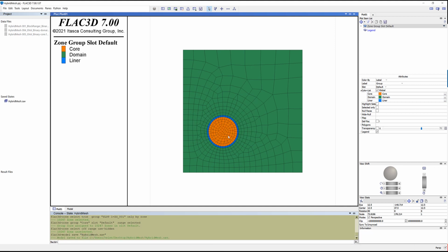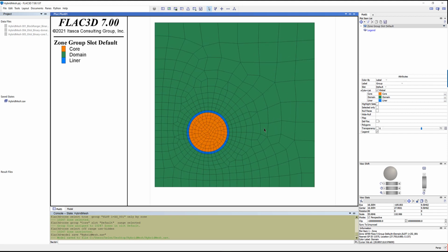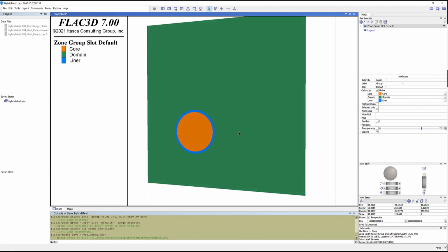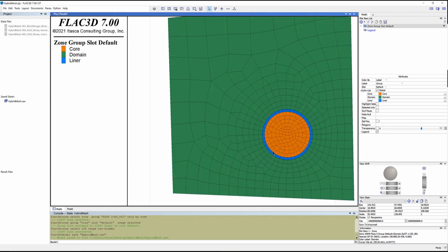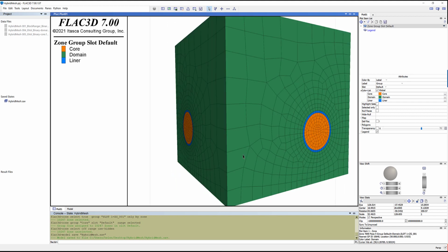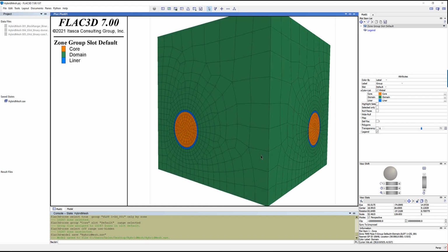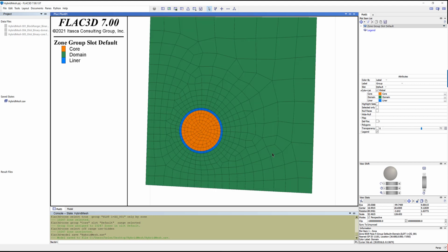Now the model state is visible under saved states in the project pane. By saving the project, the current project state is saved into a project file. By saving the model state, the current state of all the model components is saved into a save file. Any saved model state can be restored, so it is useful to periodically save models that may take time to solve. By restoring the saved model state, you do not have to rerun all the previous model commands to review the modeling results at that point. You could also continue modeling a new construction stage or add different parameters from some saved point.